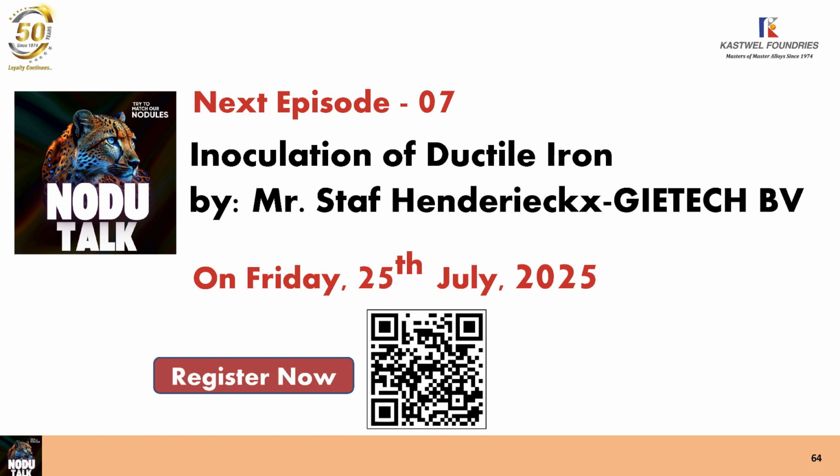And in very, very special cases, you can use a higher amount. When the initial sulfur content is much too high, you use a higher amount. But pay attention then that the slag removing is much, much more important and will be more difficult. That's the first. The second thing was, in a thick casting, how can we prevent dross?